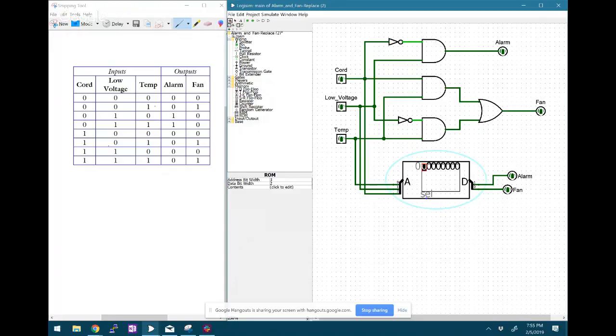So the way this works is on my inputs, you've got your 0, 1, and 2. So if I turn on temperature over here, we're now on the 1 spot, right? 0's on the left, and then as soon as I turn on temperature, which is in slot 0, we now go to the 1 slot. And it keeps going down the line. So if I do voltage, now we're 2 in binary, so that puts us in 2, and it just keeps going.